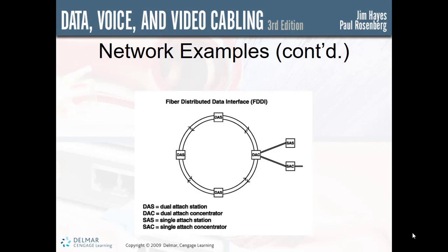However, several developments allow for the use of simple wires for high-speed signals. The first development is using twisted pair cables. The two conductors are tightly twisted, 1 to 3 twists per inch, to couple the signals into the pair of wires. Each pair of wires is twisted at a different rate to minimize what we call cross-coupling. Then, balanced transmission is used to minimize electromagnetic emissions.